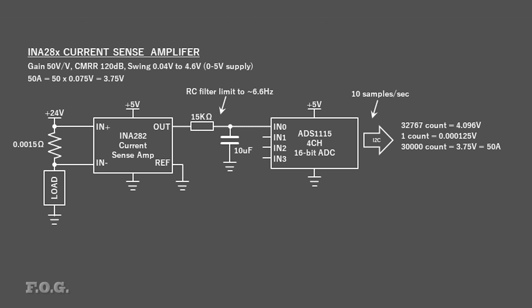So the calculation for the current would look like this. For example, if the result was 320 from the ADC, then the current could be calculated as 0.53 amps. Unfortunately, however, I did encounter a number of frustrating issues that I needed to address with my design.